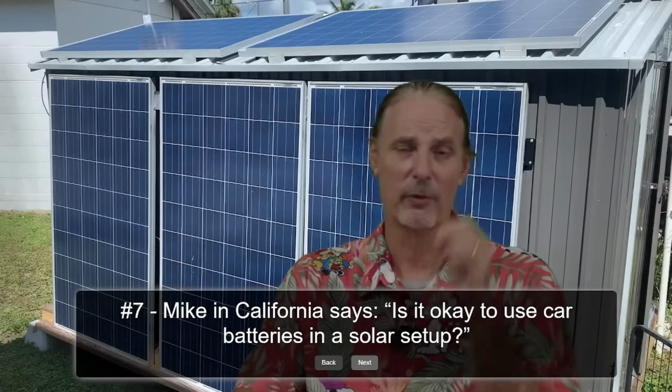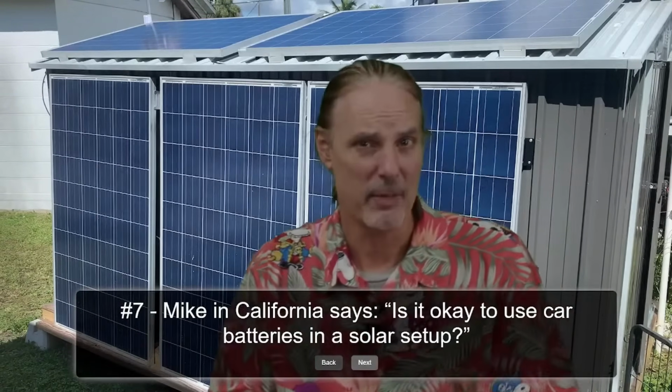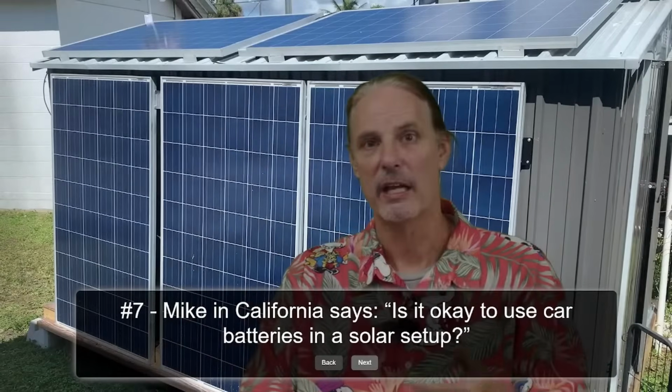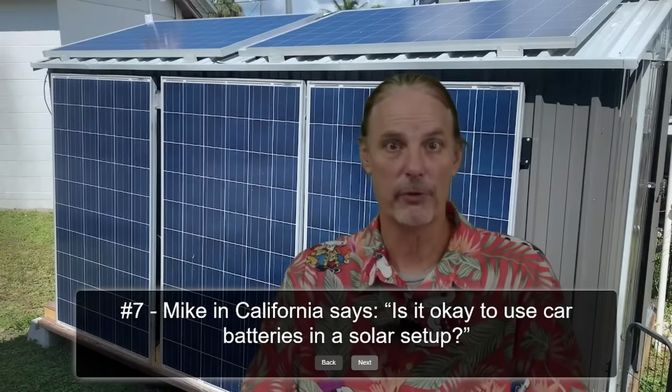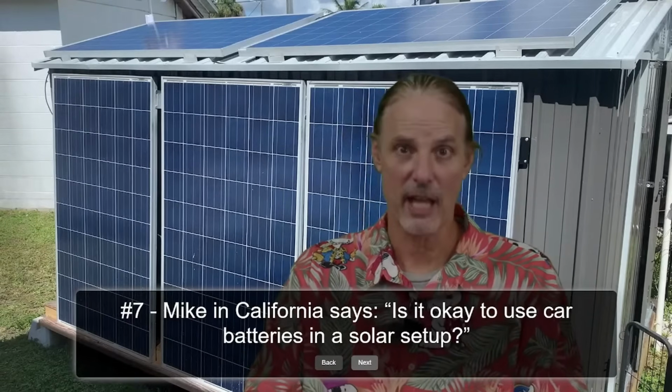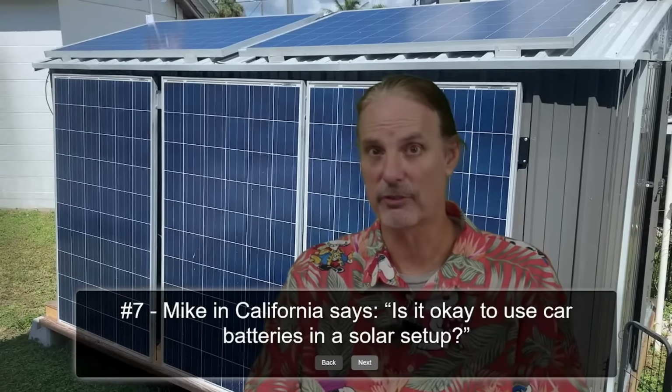So you've got to be very careful to shut off early, and that means above 50%. That means that if you have a 100 amp hour 12 volt solar system running on lead acid, technically you only have a 50 amp hour battery because you can't use it past 50%.